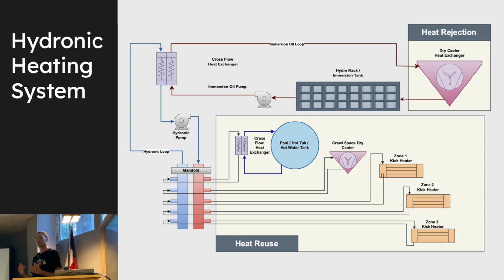It's about designing the system properly. There's a lot of pump sizing, radiator sizing, heat exchanger sizing. Make sure everything's optimally designed for your coldest day. Maybe it's overkill. Maybe the parts are 10 grand more to design it for your coldest day. So you say, screw it. We're not going to design it for the coldest day to save money. And maybe on that coldest day, you don't tear out your natural gas heating system and that picks up the slack. There's a variety of ways to do it. You can kind of split it up however you see fit. All these off-the-shelf components exist, and then you piece it all together.